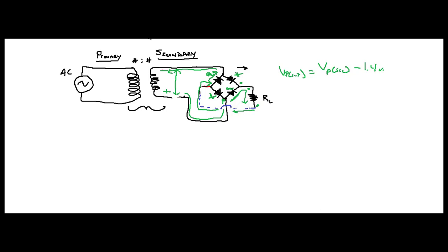Now look, when you have these diodes, they're going to look like this. And usually they have a stripe on one side or the other. When you look at them in schematic format, this stripe they have on the diode is this little bar right here. That's what it means. So it helps you orient them. So conventional current flow goes this way.